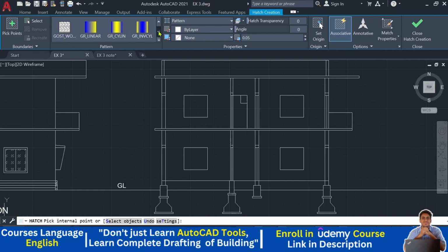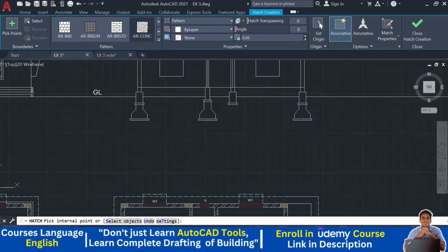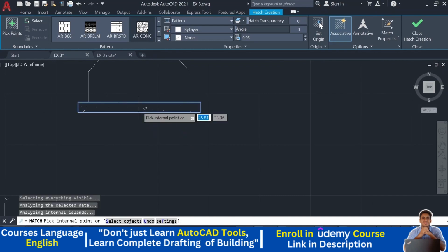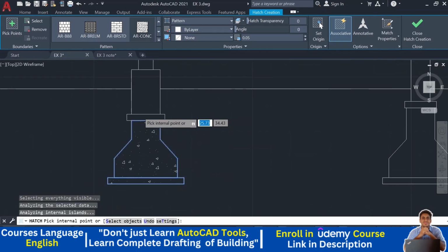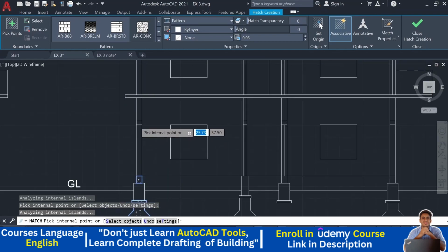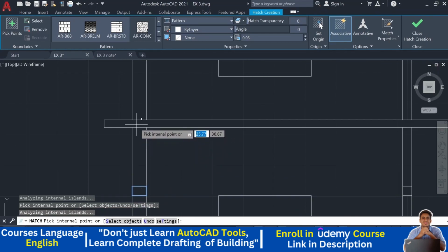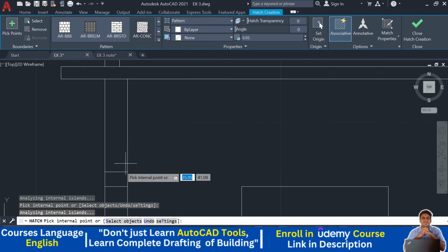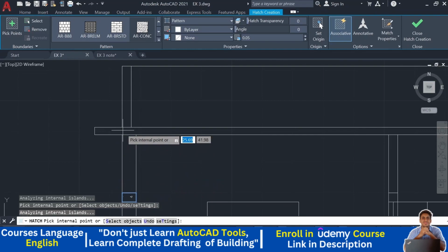So first, whatever the concrete structures are there, or structural components or concrete components are there, so that I just hatch first. I just take the concrete hatch where it is. Okay, this is our concrete hatch. You can see this one, and I just do the hatch for concrete. 1, 2, PCC 3, plinth beam 4, lintel 5, slab 6, again lintel, again the slab.